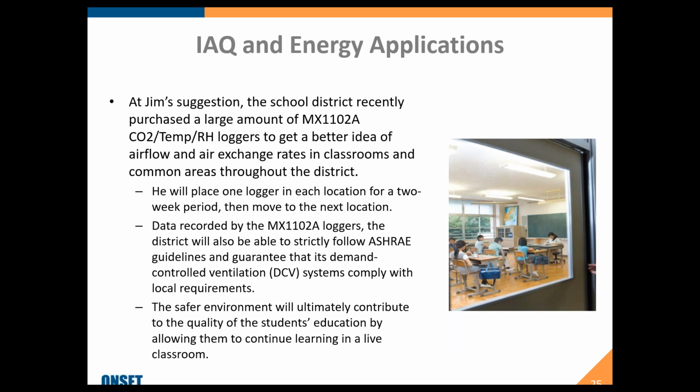One tip, if you're using this logger: you want to have it in a spot that's not next to an open door, or a door that opens and closes a lot, or a window that's going to be opened and closed a lot in the next few weeks. Put it in a space maybe 6 feet up and off a little bit, and that's going to give you a truer idea of what's going on.